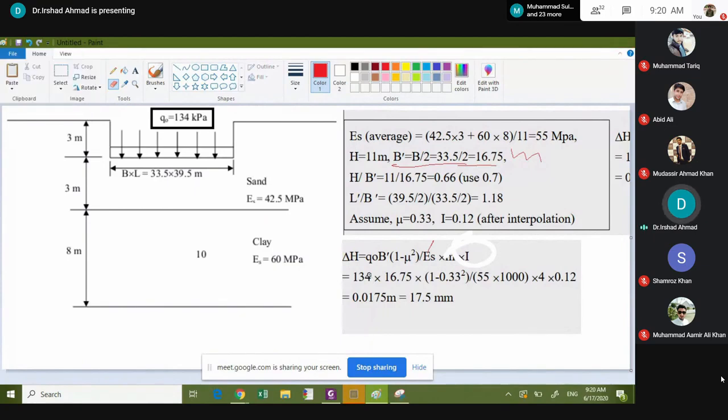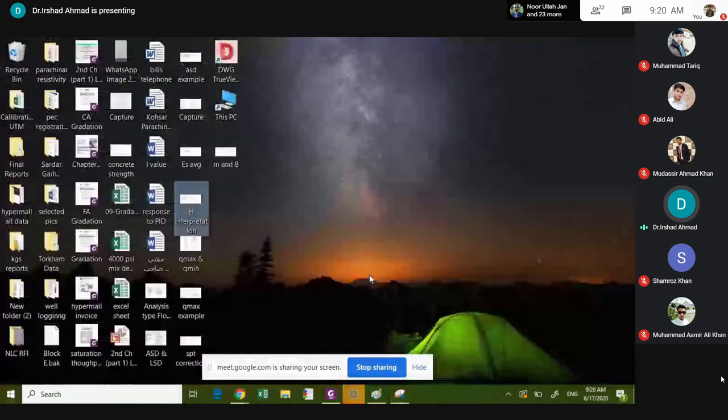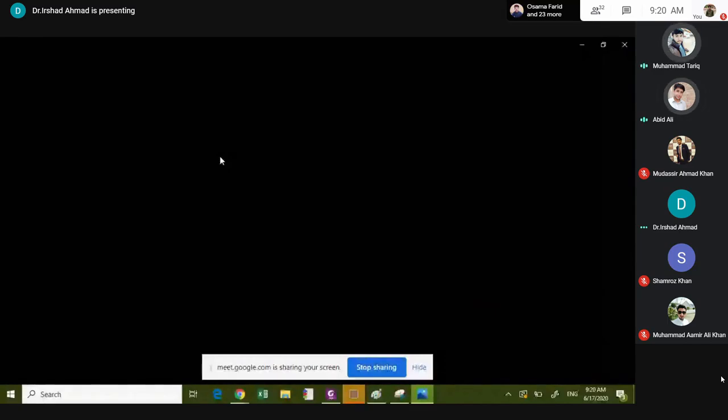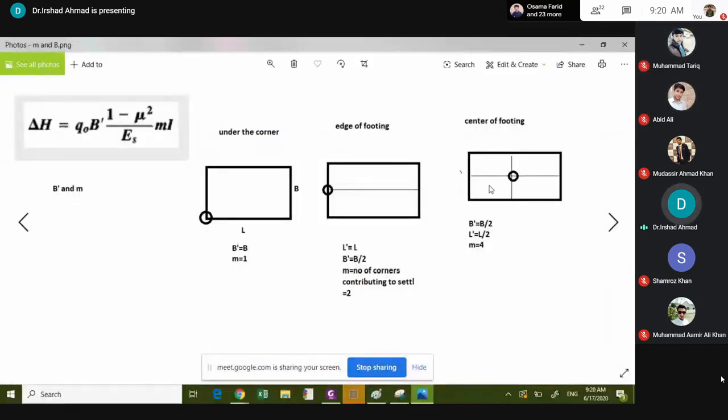आप मेरे ख्याल में उस वक्त नाश्ता कर रहे थे जब मैं ये बता रहा था। ये देखें, when you want to find settlement under the center of footing, you see under the center of footing you divide the whole footing into 4 small rectangles. You find settlement for a single rectangle and then multiply by 4 because there are 4 rectangles. M is equal to 4.